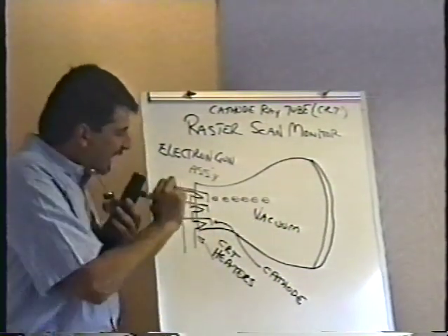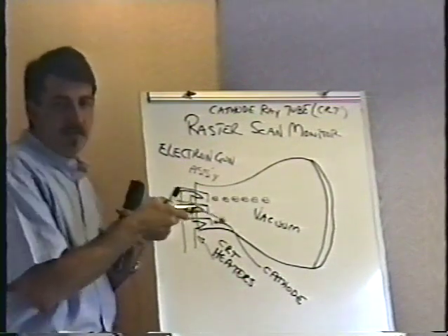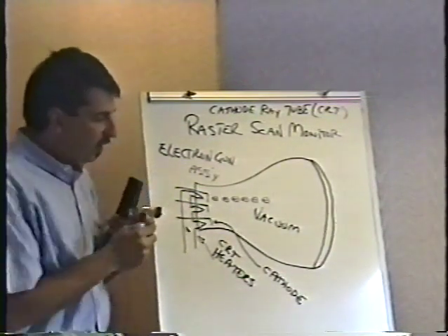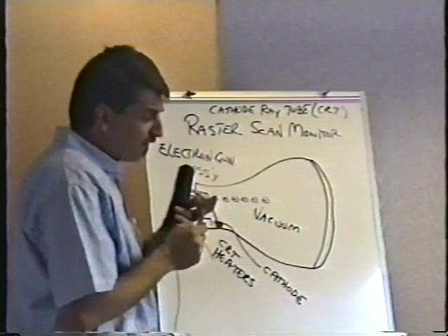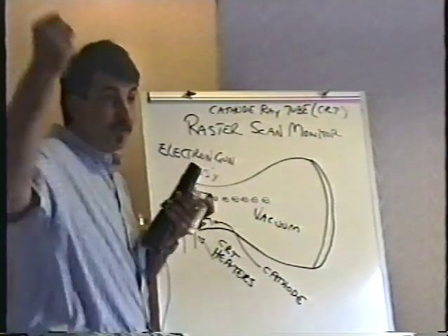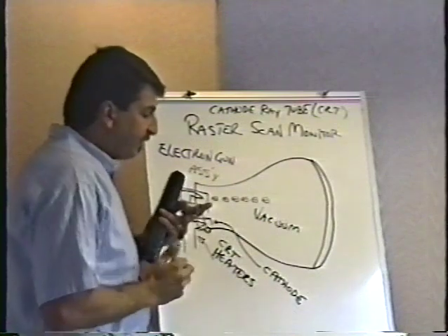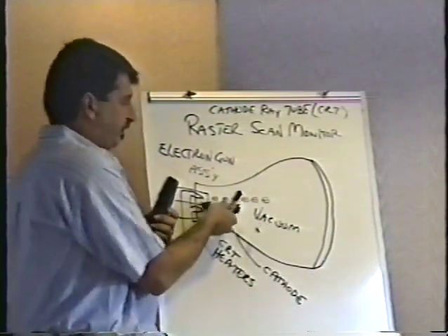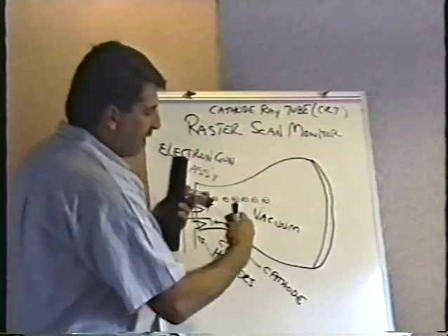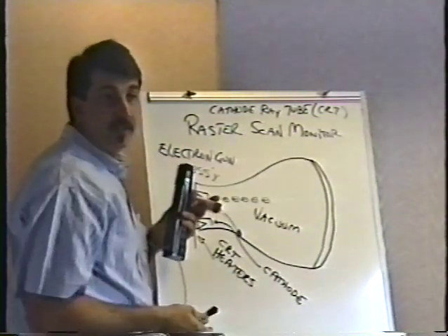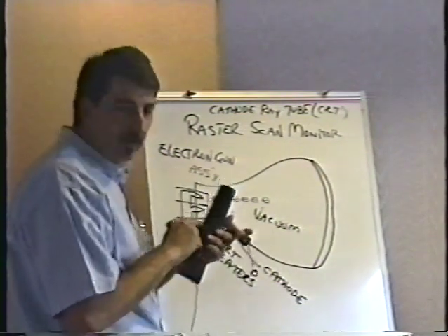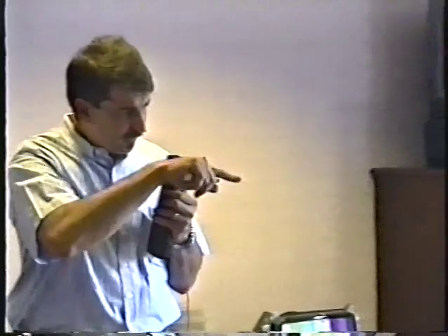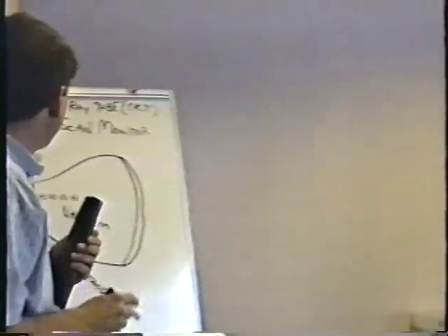Well, they originally suck the air out of the picture tube, out of the end of the electron gun assembly. They can't get it all out. So they've got this little thing, it's called the getter, this thing that's hanging out here. And this is filled with flash powder, like the old-fashioned photographers used to use. When they first fire up the picture tube at the picture tube plant, wherever that is, this thing flashes and burns up any oxygen that's left in the picture tube, any small amount of oxygen. It gets the oxygen out. Hence it's called the getter. Once it's used up, it just sits there. I'll pass this around so you can kind of take a look at it. Careful, the glass is kind of sharp, so don't touch it.